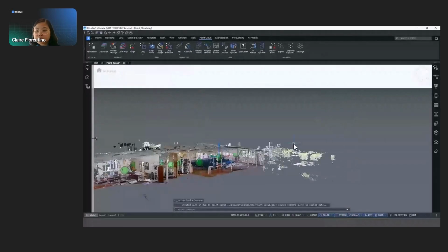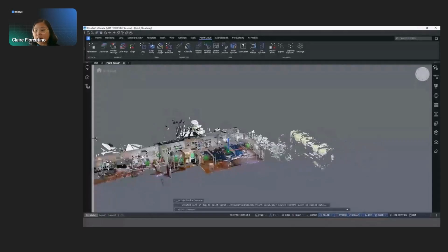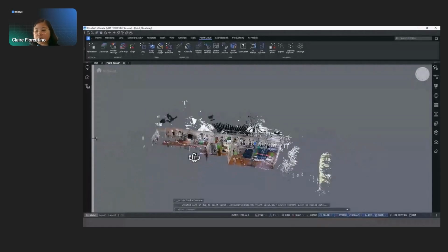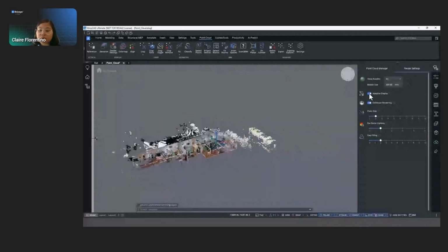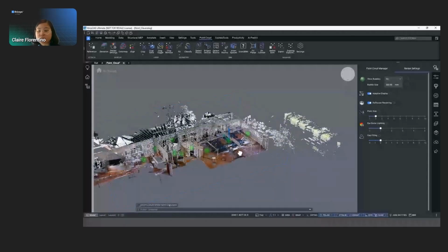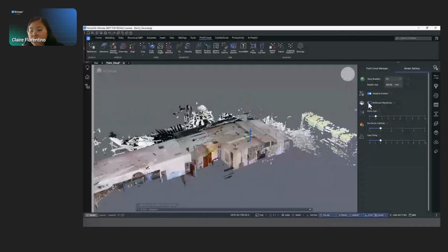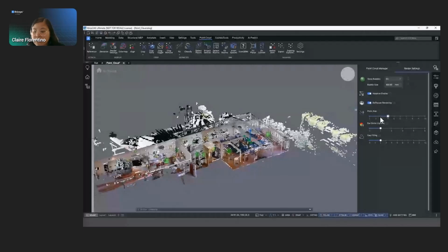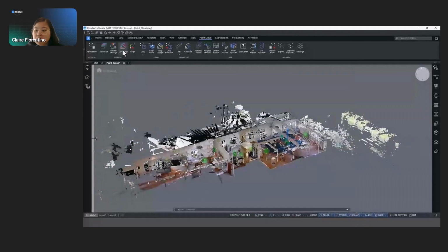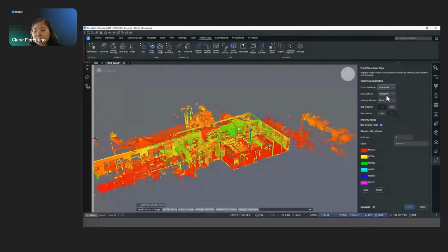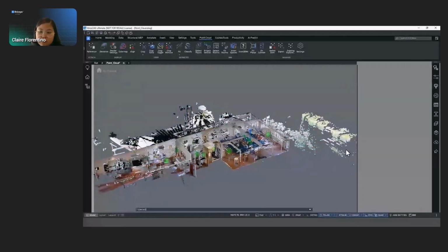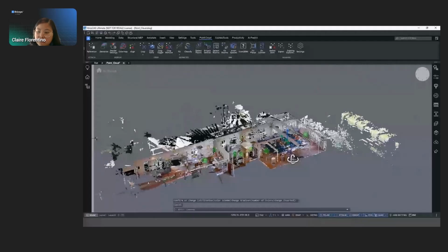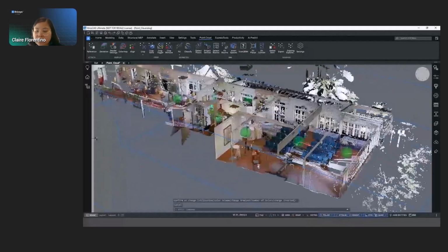So once this is in, you can proceed to inspect and pan around your point cloud scan, which BricsCAD does quite smoothly. And you can change some render properties, like here on the right side, you'll see that panel. You can turn on and off the dollhouse rendering, change your point cloud point size, adjusting the eye dome lighting, do some gap filling. You can also change your preferred color map, whichever is easier on your eyes. But for today, we'll leave it at scan style to reflect the scan colors.